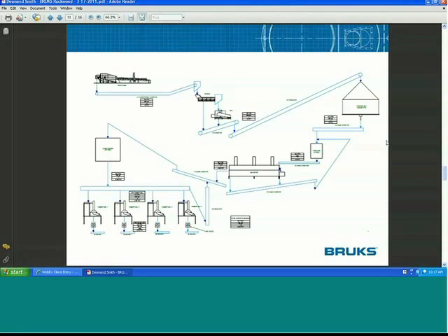We originally proposed this general arrangement here. The upper left diagram is of a truck dumper. The chips were all coming in from off-site preparation. As chips, they would come through the truck dumper and go through a screen. The overs of the screen would go through a hog so that we could reduce it to a nice uniform small size. This would go over to the upper right-hand side. That's a silo that would store about three or four days' worth of chips on site.